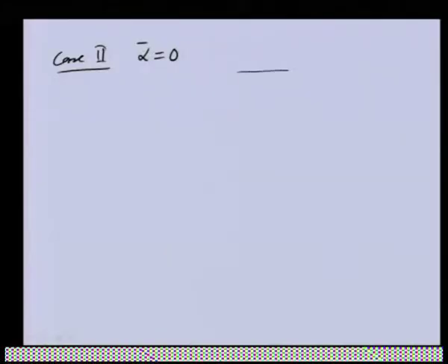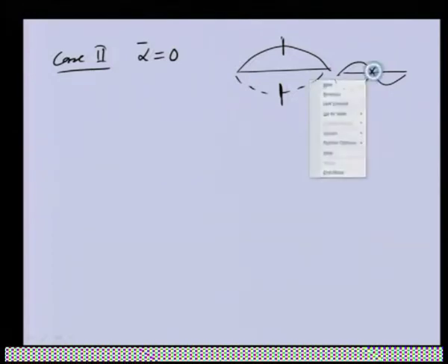Generally, let us say there is a simply supported beam and the disk is at the middle. So, during whirling it will have pure translatory motion, it will not tilt, and the same way we can tilt it without giving the linear displacement. So, the other extreme will be this one, in which the disk will be tilting about the opposite direction.